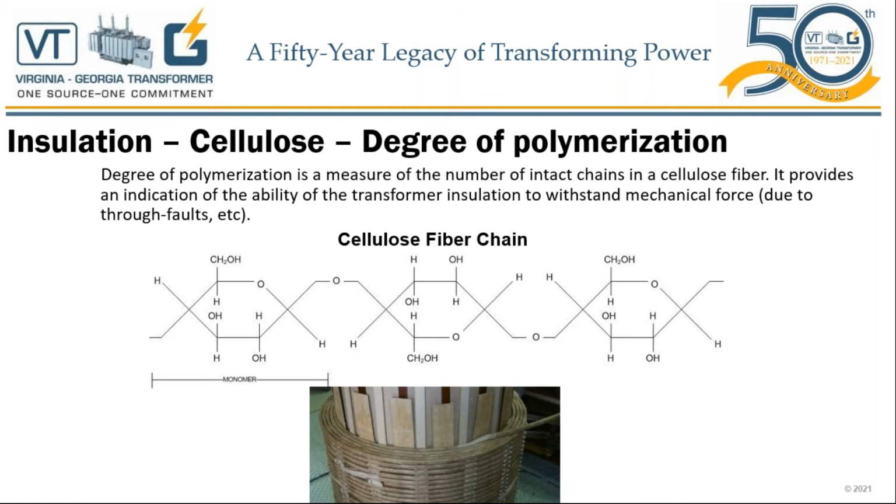Imagine that we overload our transformer for 3 months, in hot conditions, and run them really hot. Then a lot of moisture is going to break away from the cellulosic fiber chain. When something leaves, this is a typical atomic structure for anything, including ourselves as human bodies. As we age, we shrink. As the cellulosic material, or the insulation, ages in transformers, it shrinks and causes the windings not to hold the jacking pressure anymore. They need to be held against the short circuit forces.